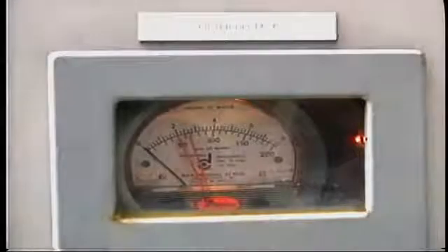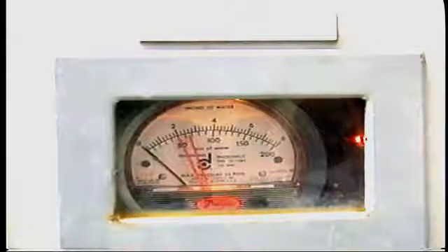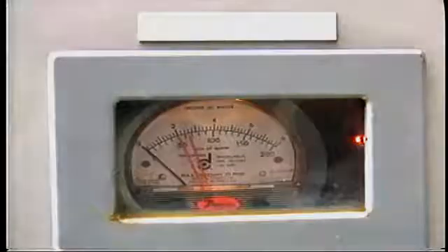The pressure drop across the filter will indicate when it needs to be replaced. On standby or peaking units, this task can easily be performed when the unit is out of service. However, on continuously operated base load units, automatic continuous filter cleaning is usually installed. The provision of clean air is absolutely essential, as the ingress of dust and other particulate matter may block cooling passages and may even cause grounding and consequent damage to the insulation.